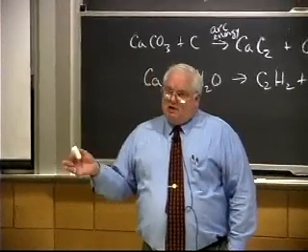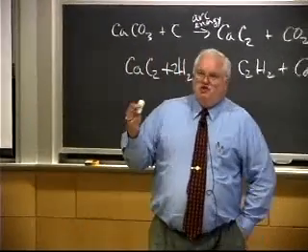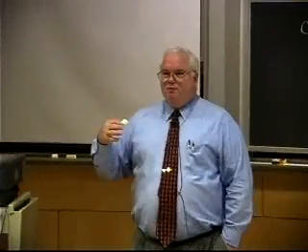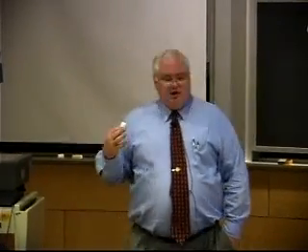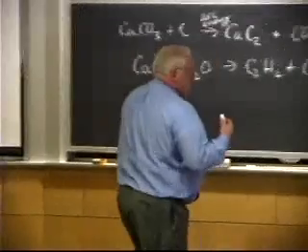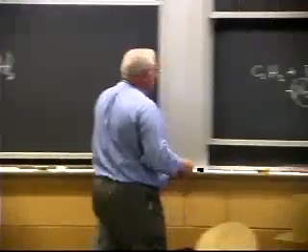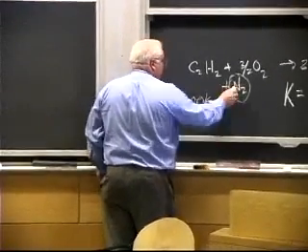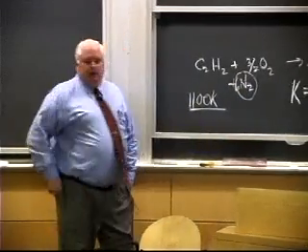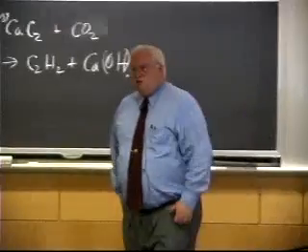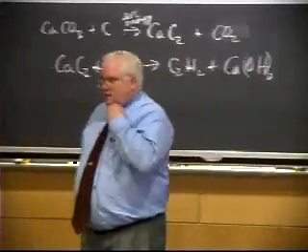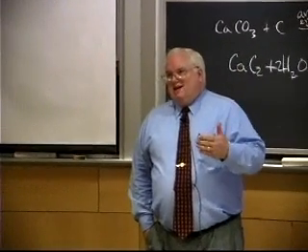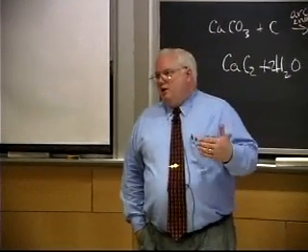And if I'm getting, let's say, 3,300 Kelvin as an adiabatic flame temperature for acetylene burning in pure oxygen, I'm only going to get 1,100 Kelvin or so if I have all this nitrogen around. And 1,100 Kelvin is going to be 1,700 degrees Fahrenheit. And so it's very hard to even get to 2,000 degrees unless I do something to preheat my incoming air.